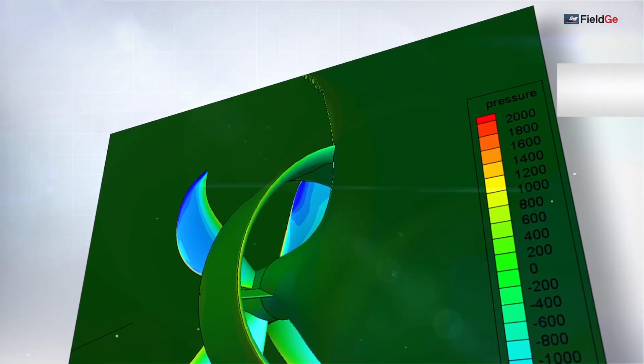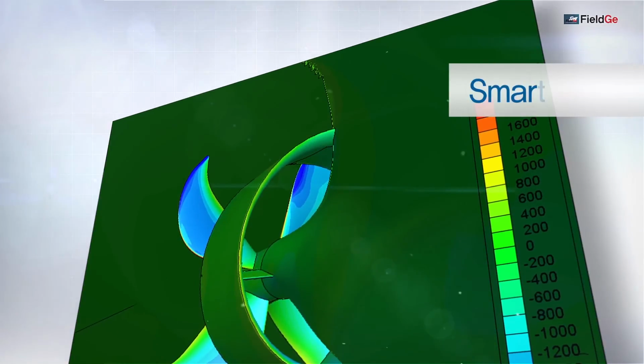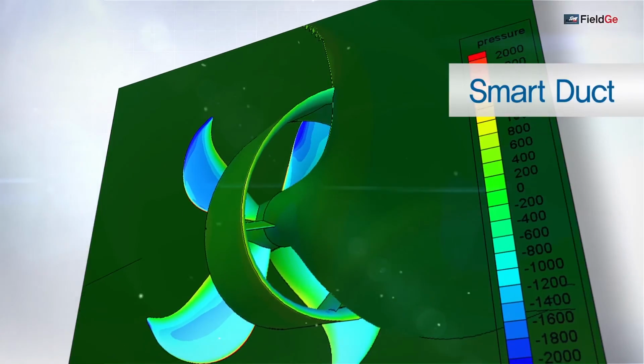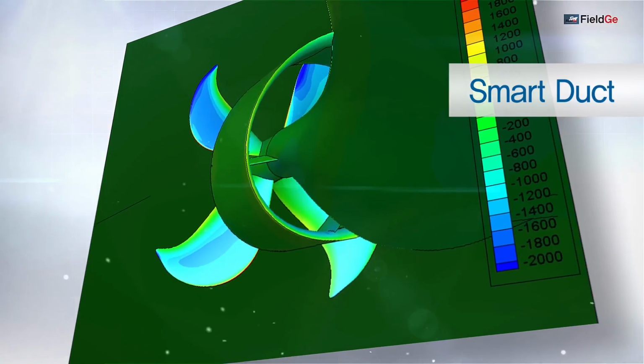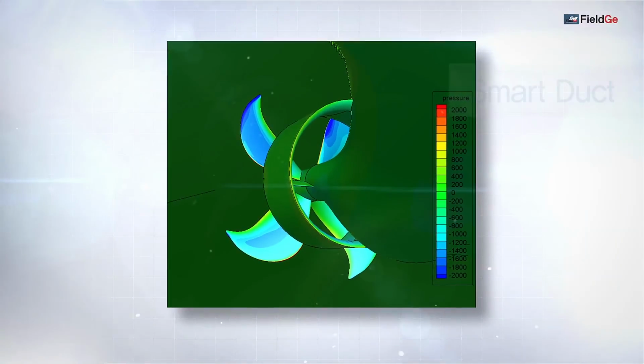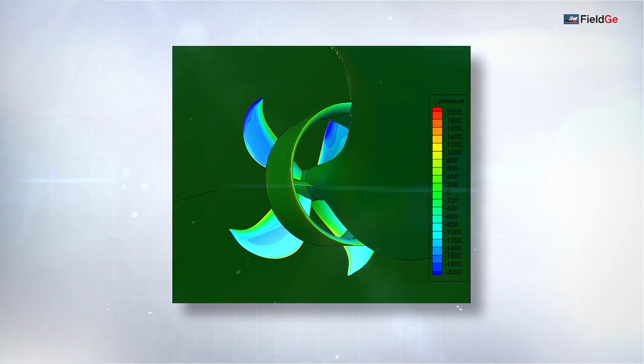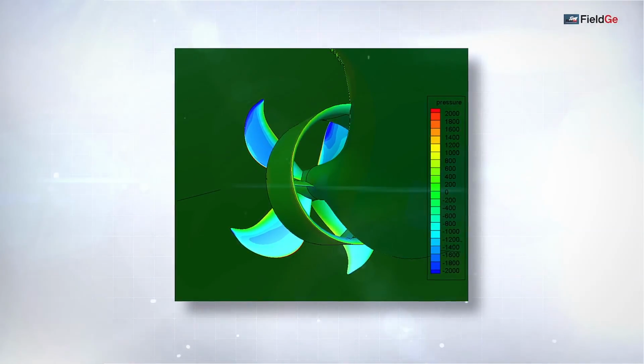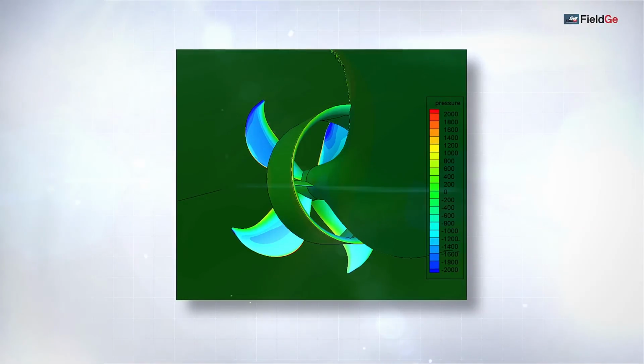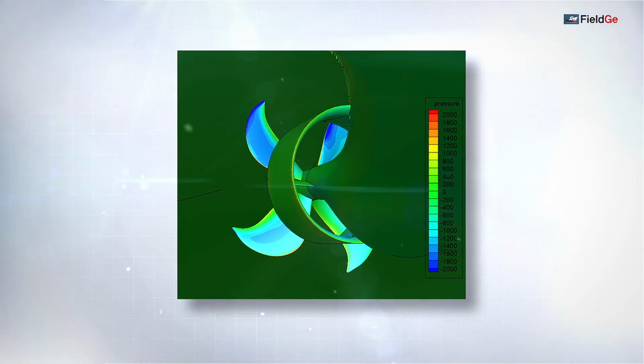Smart Duct is placed in front of the propeller location. It reduces swirl motion generated from the bilge area. Also, it controls the secondary velocity vector through the device attached to the duct. Thereby, it can improve propulsion efficiency with favorable velocity distribution. The Smart Duct is an energy-saving device developed for full-form slower ships.